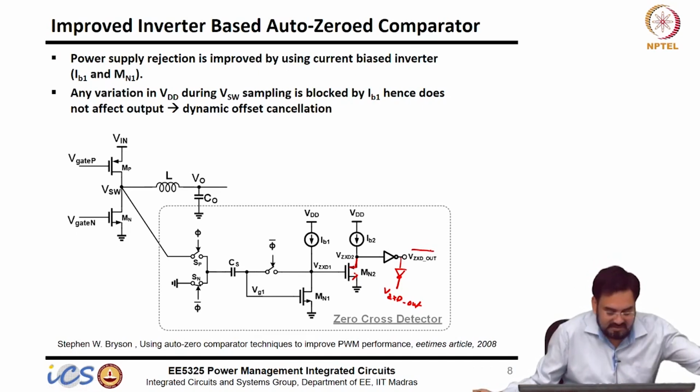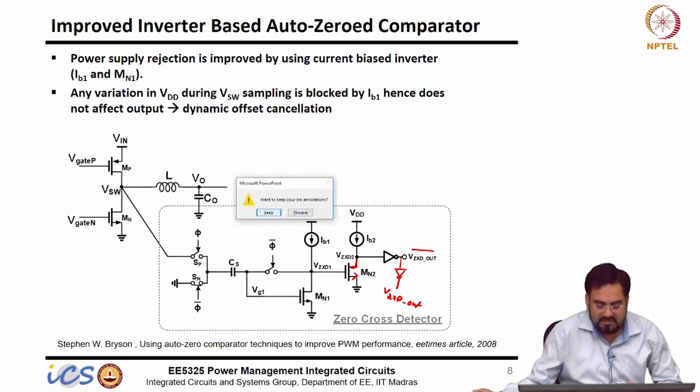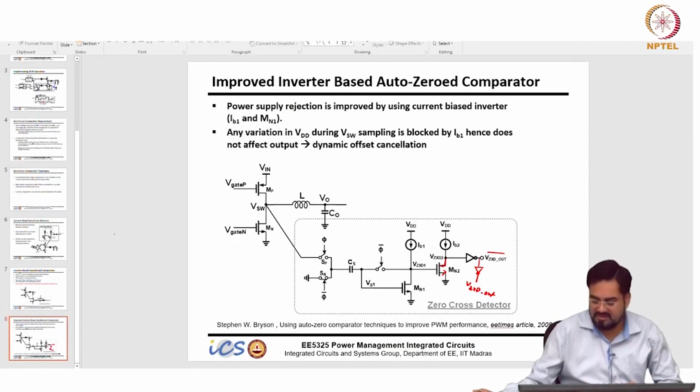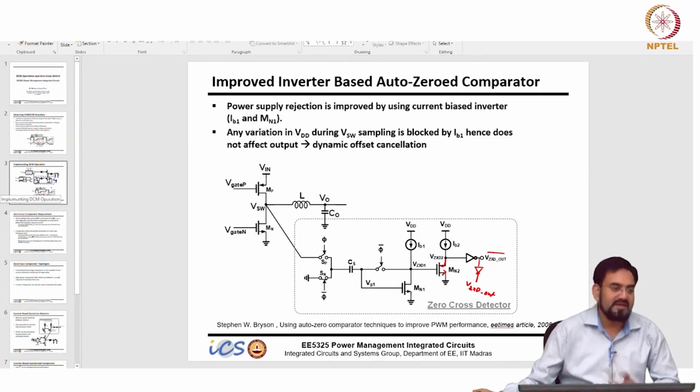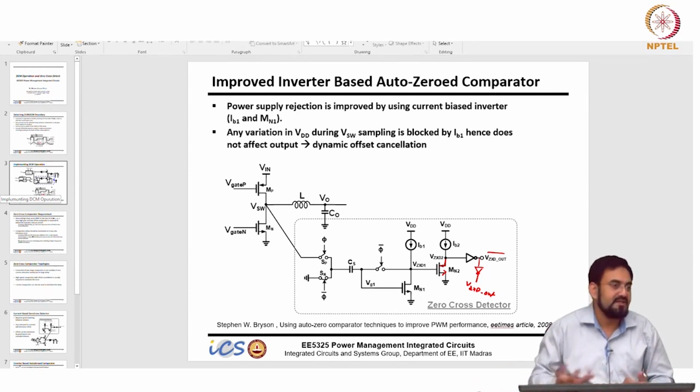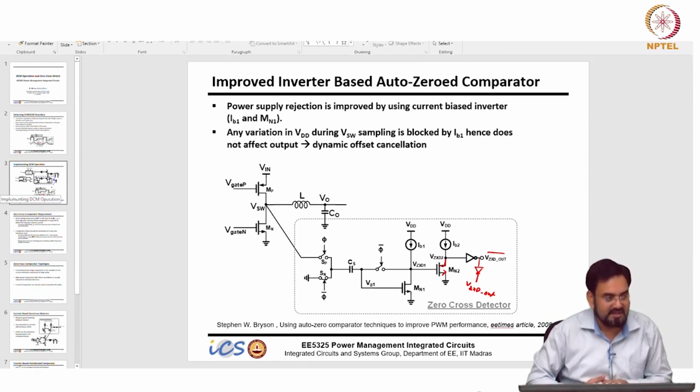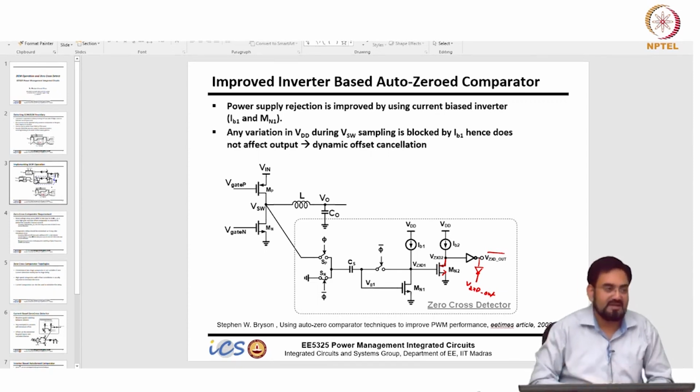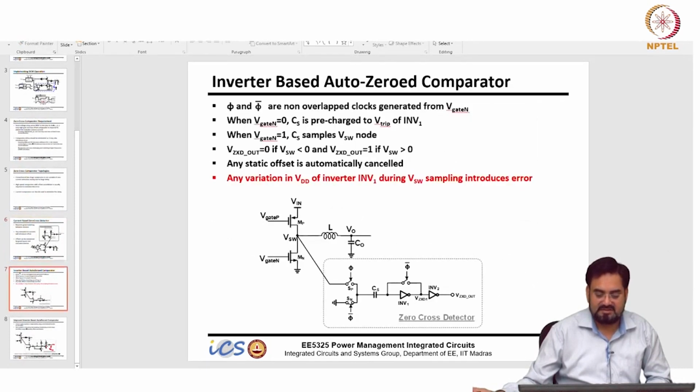So these are some techniques to design a zero cross detect comparator. But these are not the only techniques. If you know any other topologies which can work with a very low offset and high speed, then you can use that. You are not always forced to use these kinds of circuits. Okay, but this is simpler, and another advantage is that delay is minimized here, because the number of transistors is not that many. In an inverter, you have only 2 transistors, simple.